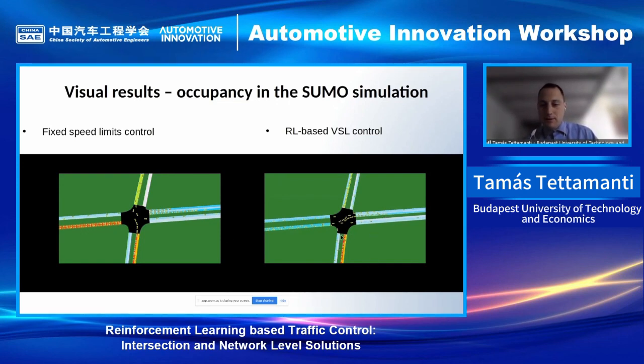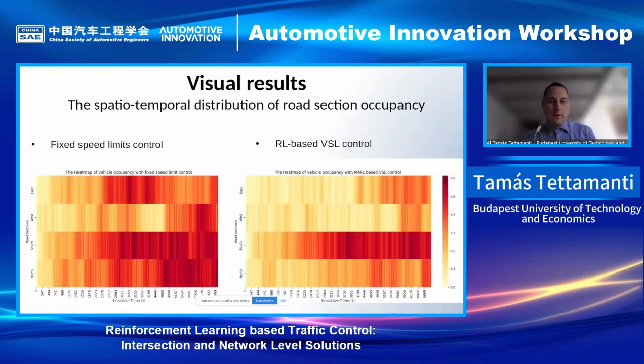But you can see also a leg on the south, which is quite similar on both sides. And this is due to the limitation of the current fixed time traffic signalization. So of course we cannot do a miracle, but still we can ameliorate the whole system efficiency. But here on the south leg, the left turn green light is so small in time that we cannot really ameliorate this part. But in all, the whole system provided better results.